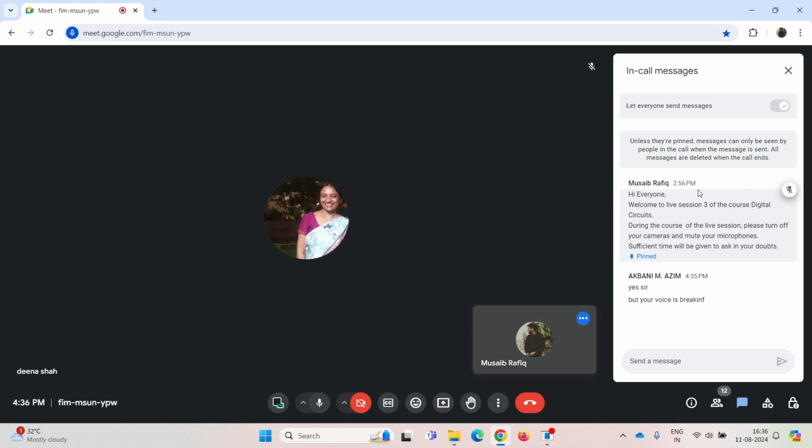So I was just referring to this implicant. Basically, the minterms and maxterms that are present are your implicants. Prime implicants are the set of squares and rectangles that you can create using the K-map rules. And an essential prime implicant is a prime implicant which covers a minterm that is not covered by any other term, and it is always present in your final solution.